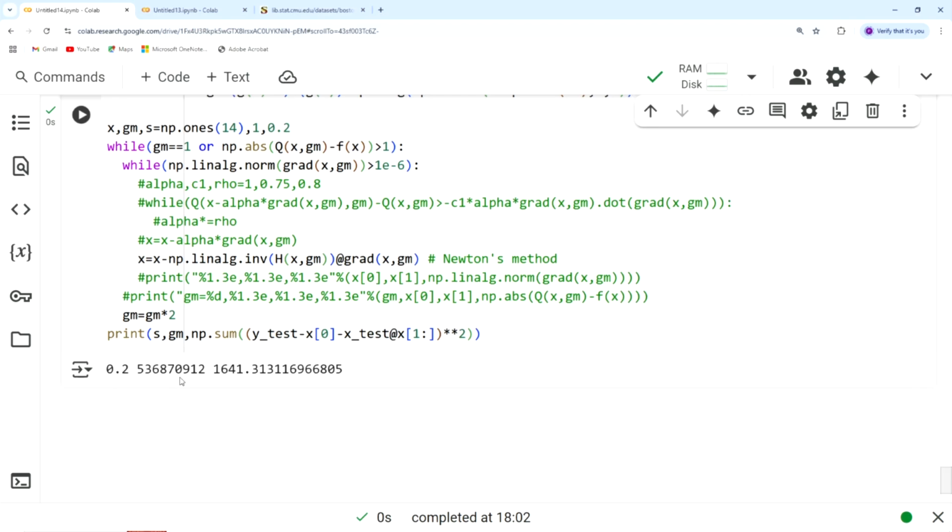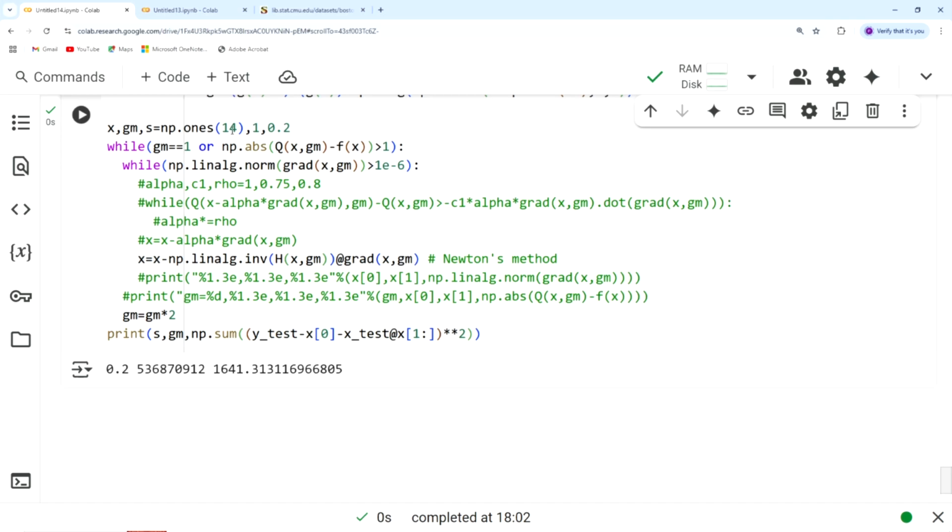But one thing that you need to note is that the value of gamma is huge again, about 536 million. In the Indian system it is like 53 crores. We usually get the right answer with a very high value of gamma, like 5.36 into 10 power 8, and that too after modifying the tolerance to be 1 instead of 1e minus 6.